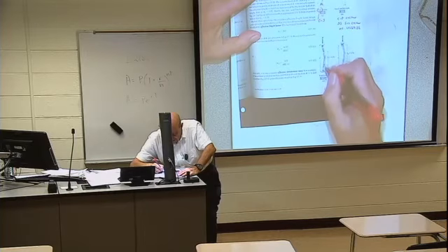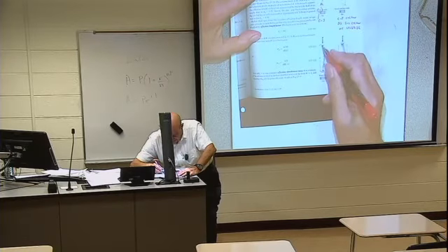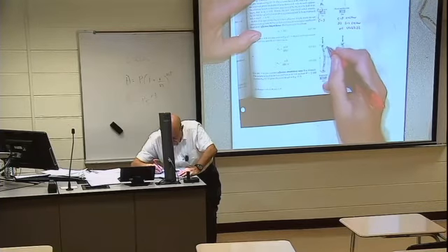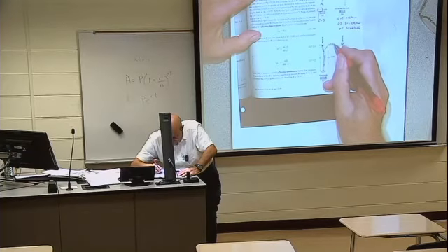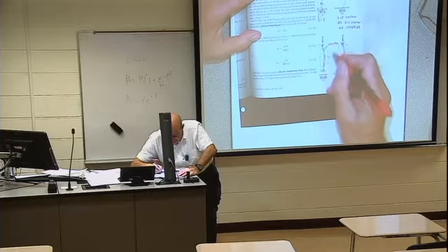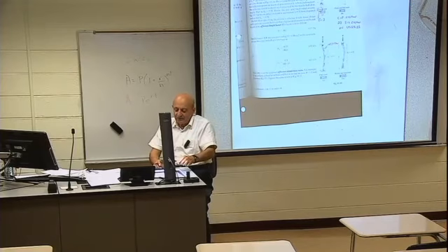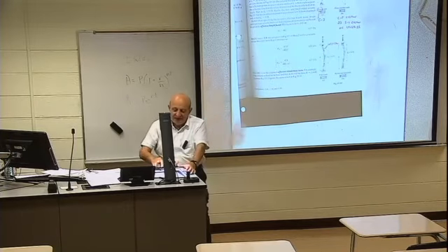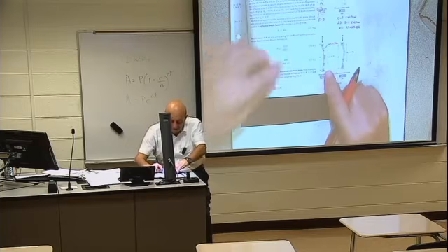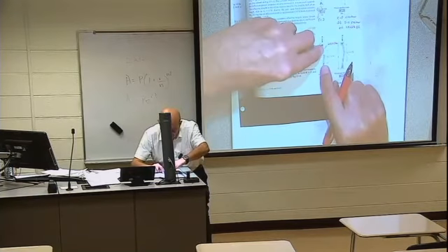Okay, here for clamped ends. So that is a buckling mode. We can find the distance actually between points of inflection. And the distance between these points is half L. So that means that the length, as it were, of the clamped beam is half, and then the beam is simply supported here.